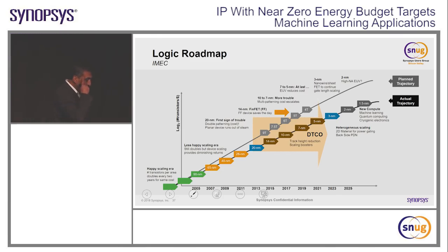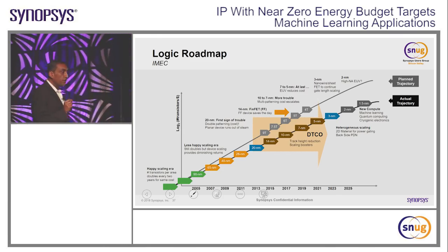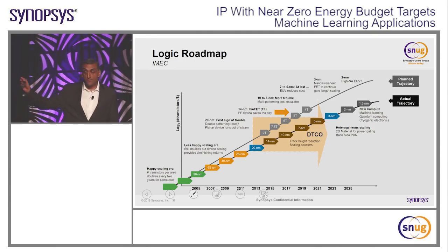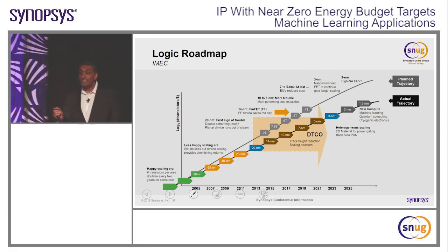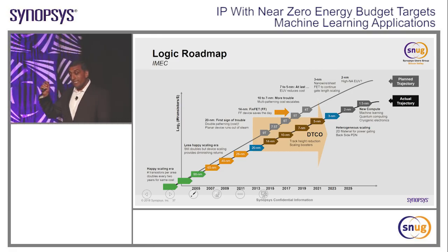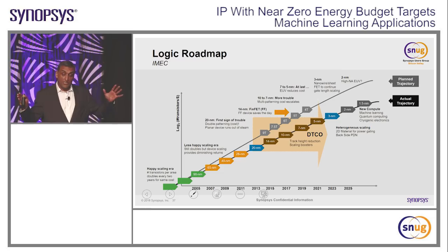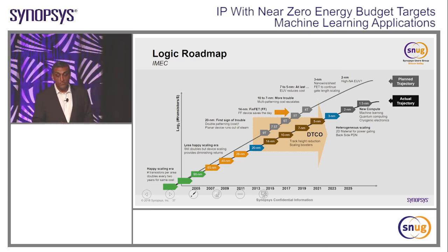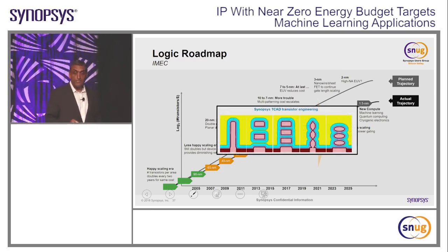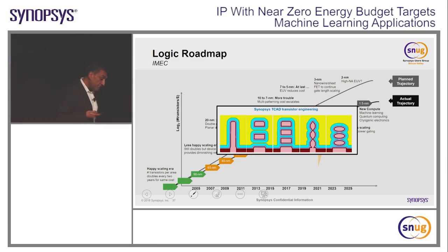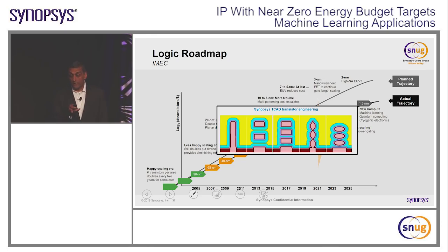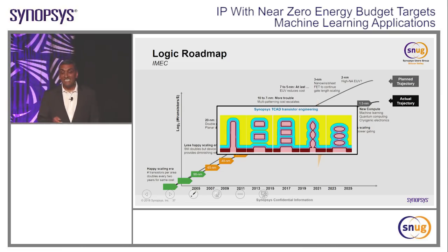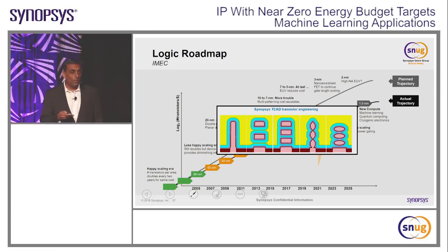This is a fascinating topic, and what this says is that you link your lithography, which is shown in this slide, with your EDA tools, your logic libraries, and your TCAD, and by linking them all together, you can do an optimization that can improve performance and reduce your power consumption. So this is an example of the transistor optimization that can be done using TCAD software. So this is comparing FinFET devices and the different types of fins that people are talking about getting below 5 nanometer. Why do I talk about this?